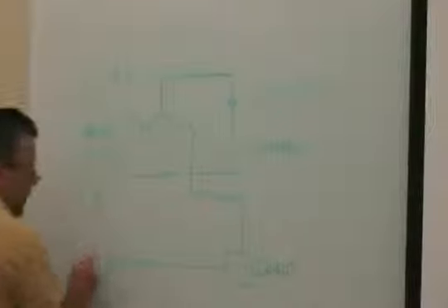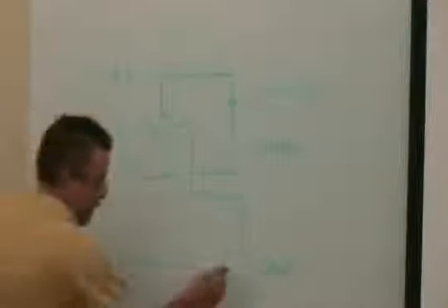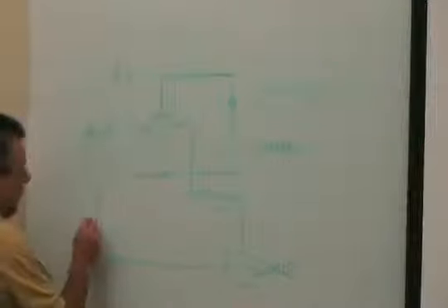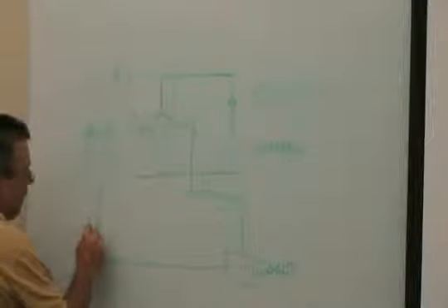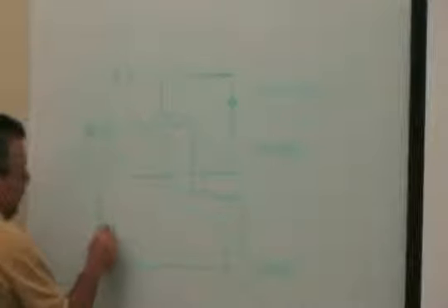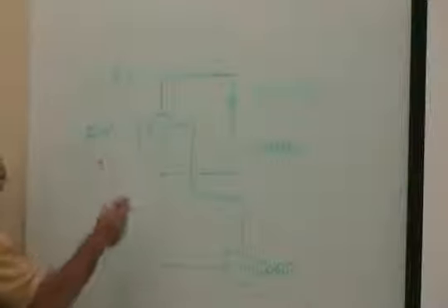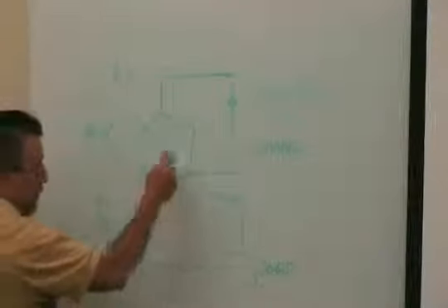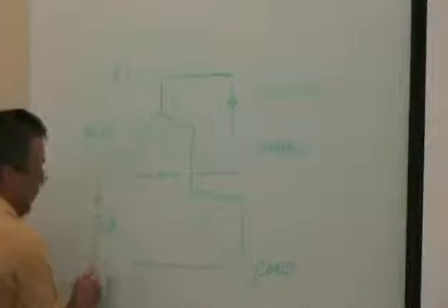In a geothermal application, I've got to insulate the condenser and add an expansion valve right here. That's the difference between water source, no insulation, only a distributor or orifice. I go into a geothermal application, add an expansion valve, and I insulate the condenser.